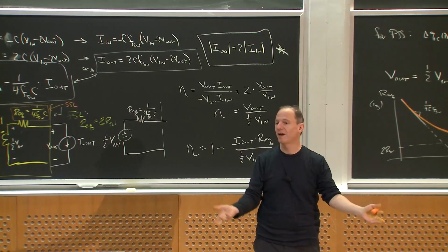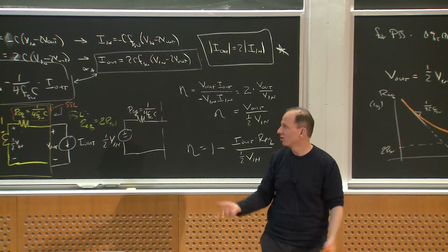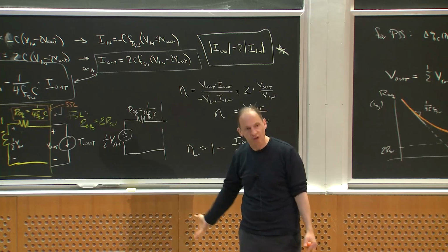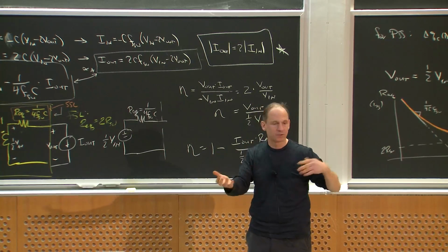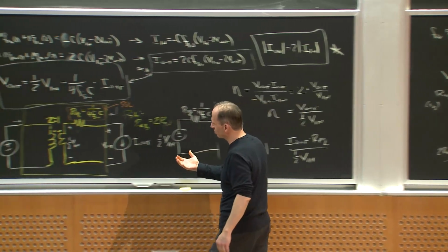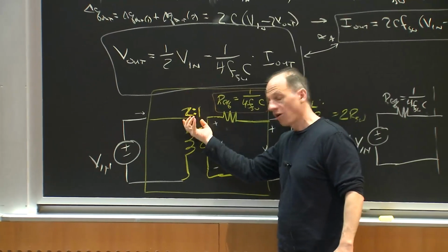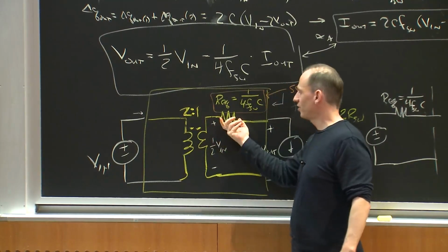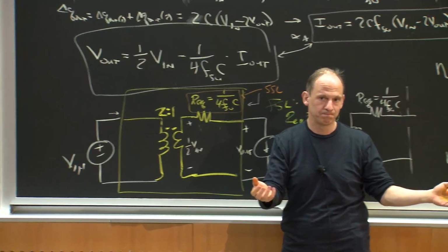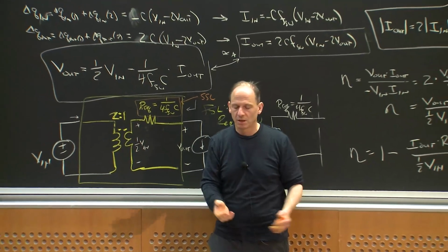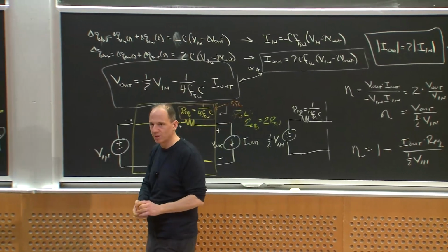And if I were to analyze any other switched capacitor converter, it's the same deal. It's some charge transfer analysis through the different capacitors, and I use charge balance, and you can work that out to being a current conversion ratio and then some equivalent resistance with a slow switching limit and a fast switching limit. We'll take this up again next class, but are there any final questions?